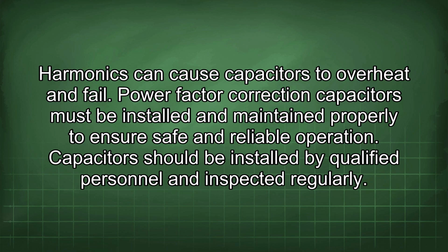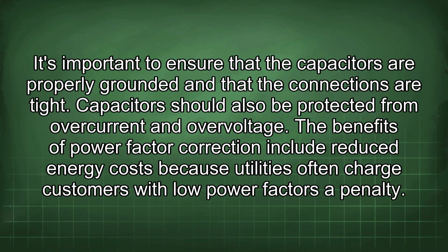Power factor correction capacitors must be installed and maintained properly to ensure safe and reliable operation. Capacitors should be installed by qualified personnel and inspected regularly. It's important to ensure that the capacitors are properly grounded and that the connections are tight. Capacitors should also be protected from overcurrent and overvoltage.